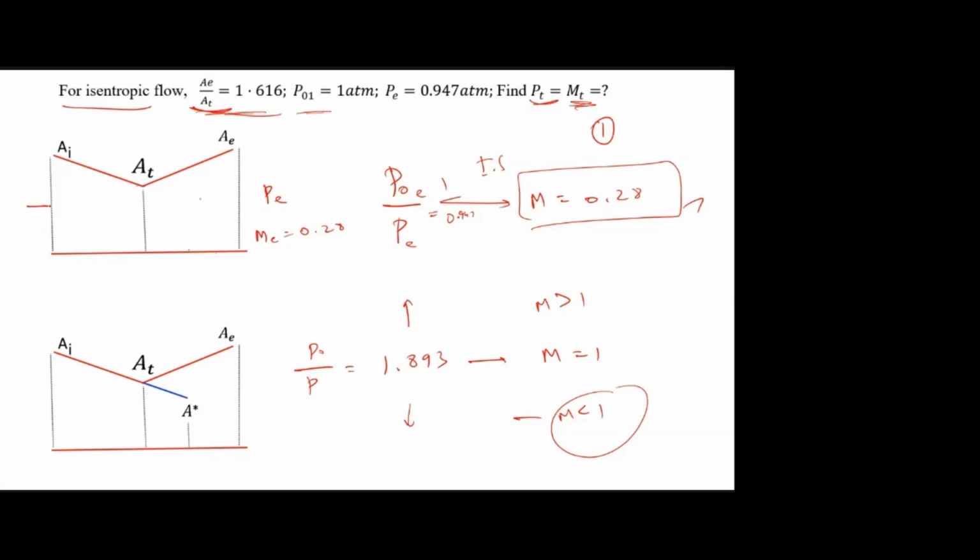As the flow is convergent, the subsonic Mach number is accelerated, not to 1, some other subsonic value. Again, it is decreased to low subsonic. Then here maybe a little bit high subsonic. Again it decreased to low subsonic. Is that clear?